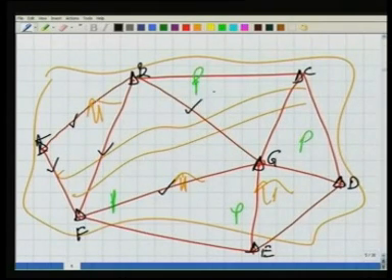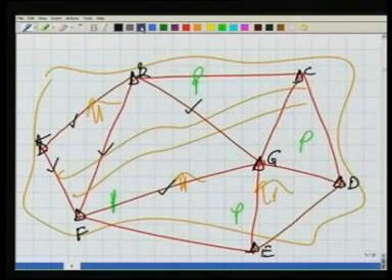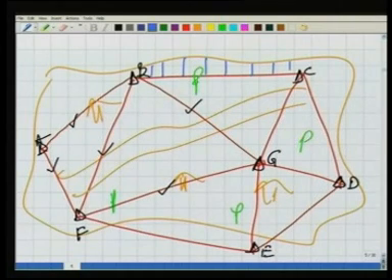I can measure all these lengths, that is not a problem, because I have ensured that these lines pass through nearly flat area. There is no obstruction. Also, taking the offset is easy. I can plot this boundary here, with respect to the line BC, also this road.